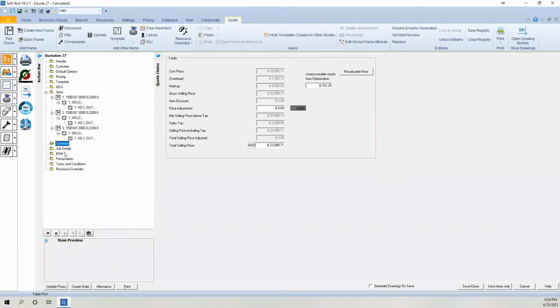Also, you can say that I know my wastage always, on average, is 3% in my factory. So I just want to put 3% average wastage for everything, all the profiles. Or some profiles 3%, some profiles 8%. So you can also put a predefined wastage factor and put that into account of your final cost. There is also the option to not put that at all, and only based on the actual cut length, you can get your cost.